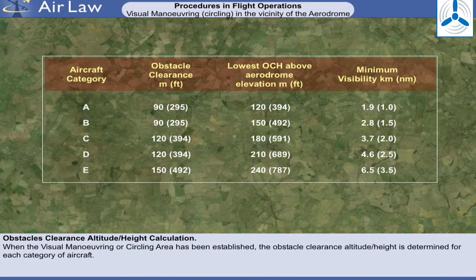After initial visual contact, the assumption is that the runway threshold or approach lighting aids, or other identifiable runway markings, should be kept in sight while the aircraft is at minimum descent altitude or height for circling. If visual reference is lost while circling in such circumstances, the pilot should carry out the missed approach procedure specified for that particular instrument approach procedure. The pilot should first make a climbing turn towards the landing runway and aerodrome overhead to preserve obstacle clearance. Secondly, he should complete the missed approach procedure.